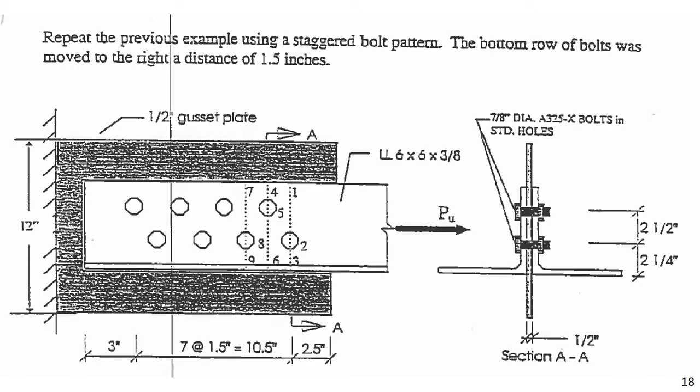So the question might be, why would you do this? When you start getting into this, there are certain limitations to how closely you can drill bolts together. If you drill bolts too close together, you end up with Swiss cheese. You end up with a plate that's more Swiss cheese than steel. And so there are certain distance requirements that we're not going to go into in depth, but that you have to be aware of. Sometimes you may stagger your bolts just so you can give that extra little bit of distance you need to meet code.